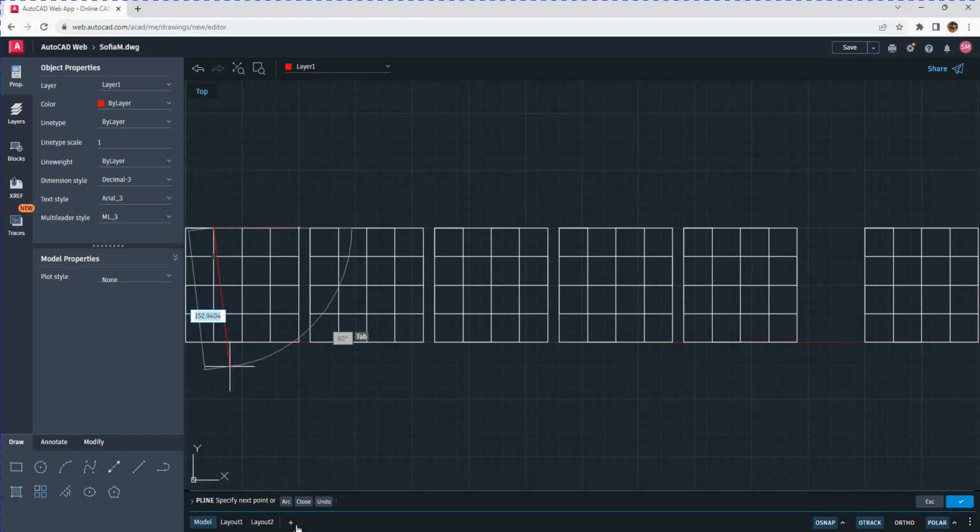And now I want an arc. So you go down here and click where it says arc. Remember that we need 3 points for the arc. You have the first one. I'm going to select this one as my second one. And my third point will be down here. There you go. Now I want to keep on with my lines. So I click again where it says line, and I go all the way over here, 2 more squares, and I'm ready for my next arc. So again, you have point 1, go to point 2, and then point 3.